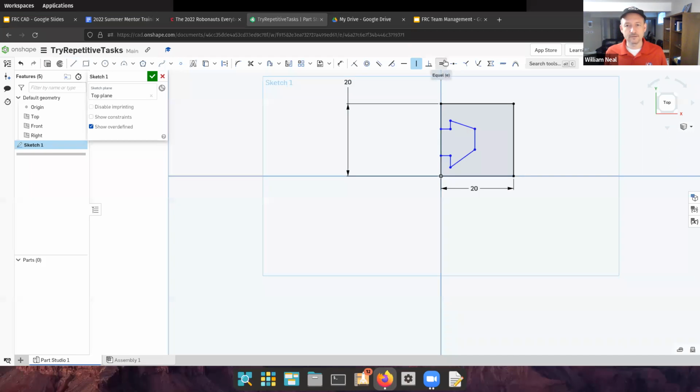And then there's my equal constraint. I want this one to be equal to this one. And I want this one to be equal to that one. There we go. I think I can probably, oh, that's still the whole line there. I can constrain the horizontal and vertical distances of my points as well. This one here, I can specify its dimension.